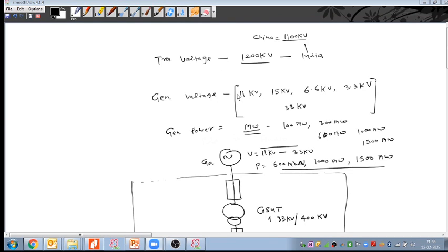Yeah, 1150 correct, Rahul. 1150 is the highest voltage, and this plant is based, I think, in Madhya Pradesh, MP, and in Bina we have this testing line of 1150 kilovolts. So 1150 or 1200 is the rated voltage. Nominal voltage is 1150 kilovolts. That is the maximum voltage that we have in India. The plant is based in Madhya Pradesh. The place name is Bina, I think.